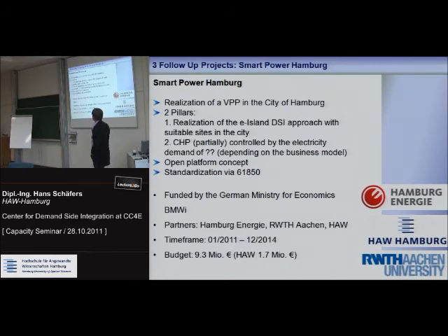The question is whose electricity demand is actually going to be covered by the CHP. Because the interesting thing is that if we do a schedule for a lot of sites and then monitor those sites and we see a deviation and say we're short, we don't have enough electricity, it could be that the overall system is long at this time. So our deviation is not really a problem.